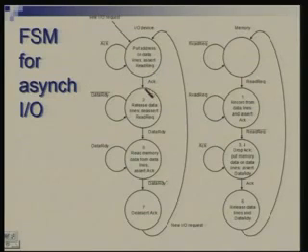As soon as the acknowledgement signal is seen, the device proceeds to the next state, and in this state it will release the data lines and deassert read request. On the other hand, after having sent the acknowledgement signal, memory would be waiting for read request to go down, and it will remain in this state as long as read request is 1. You would notice that the transitions in these two state diagrams occur one by one. One transition occurs here, then one occurs there, and so on.